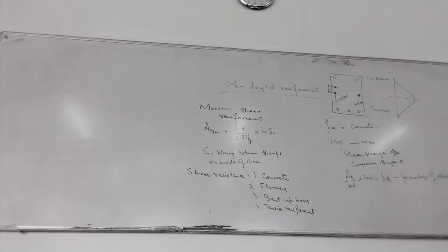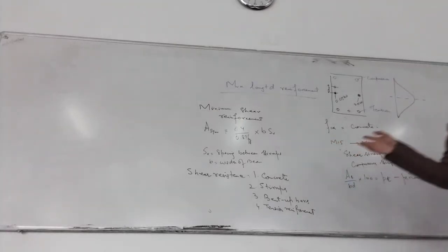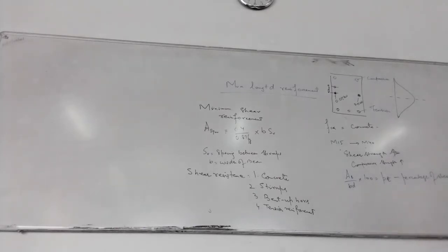Now, from where to where does the percentage of steel go? The minimum the code writes is 0.15. When we saw last time, what was the minimum steel area? It was 0.15%. And the maximum we just saw, what was it? 0.04 bD, wasn't it? So into 100 would be 4. I was wrong just now, not 0.4, 0.4 is not right, it is 4%. So its maximum would be 4% in a beam. So it has written 3 and above. So the maximum is 4%.